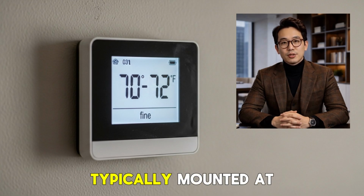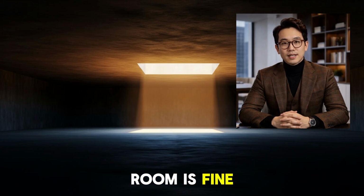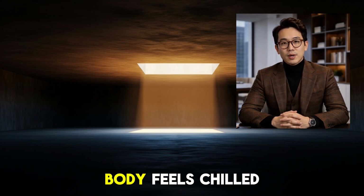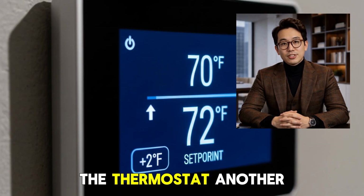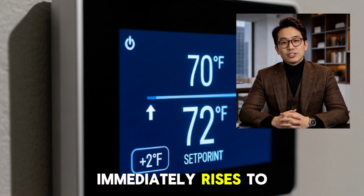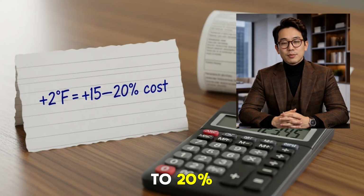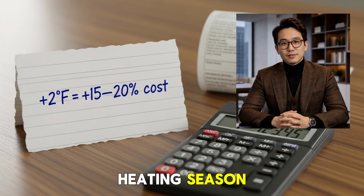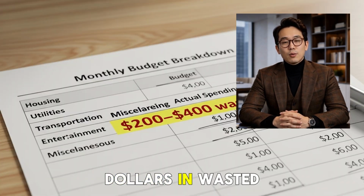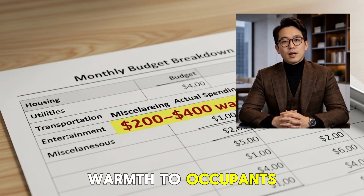Your thermostat, typically mounted at wall height around 5 feet, reads somewhere in the middle. It thinks the room is fine. But your feet are cold. Your body feels chilled. You turn up the thermostat another 2 degrees. The furnace runs longer, heating air that immediately rises to the ceiling and contributes nothing to your comfort. Your heating bill climbs by 15 to 20% for every 2 degrees you raise the thermostat. Over a winter heating season, this stratification problem costs the average household $200 to $400 in wasted energy, heating the cubic feet of air near the ceiling that provides zero warmth to occupants below.